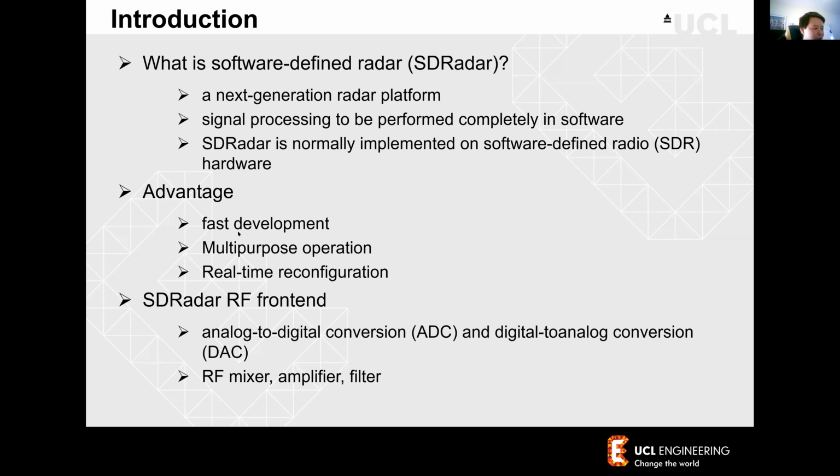The advantage of the SDR radar is very fast development, because all the signal processing is in the software. So basically you can modify it very quickly and easily, and it can be used for multi-purpose operation, again because signal processing is in software. For example, you can sense the Doppler, you can also sense the angle. That's up to how you design the system. It also gives real-time reconfiguration. When you write the code, you can configure it very quickly and run it on the